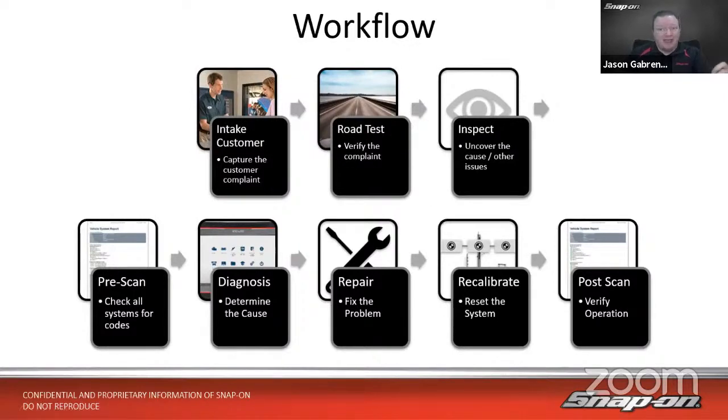I want to make sure I'm accurately capturing that customer complaint and seeing what's wrong with it. Because it might not be, "Hey, my engine light's on." It might be, "Hey, it struggles getting up a hill," or it makes a rattling noise, or it's a no start or an intermittent start. Some other sort of problem. We want to try and narrow it down at least to the neighborhood of what we want to look at.